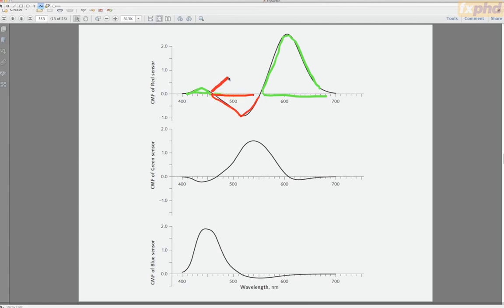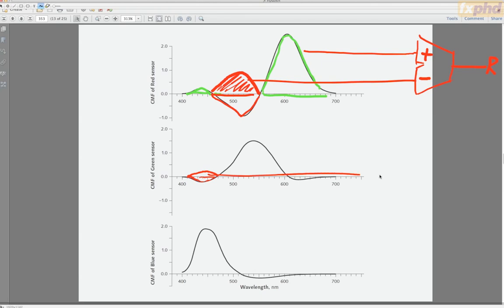So in other words, we build a camera that senses this, and then electronically we take that and this, we subtract this one electronically to produce that R signal, which will directly drive a Trinitron. And for engineering purposes, you can think, in theory, we should really have a sensor sensing that and then electronically inverting it.